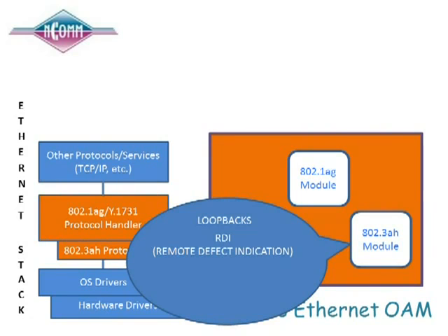Remote failure indication, or RFI, is provided as an alert to a peer that the receive path of the local DTE is non-operational. Also provided are standard compliant counters, timers, and state machines, including OAM discovery process, transmit, multiplexer, and parser. Variable processing requests for MIB information from the remote end, as well as requests by and the return of MIB variables as required, is also accommodated.